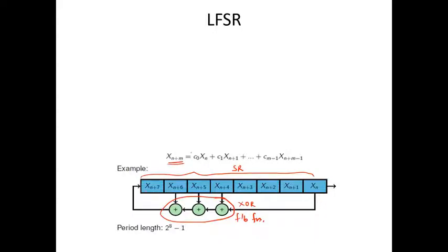It is by adding certain bits in the shift register. And the addition of those certain bits depends upon these coefficients C0, C1, and so on. So if those coefficients are ones, then that particular bit is considered in the addition. If they are zeros, it is not considered.